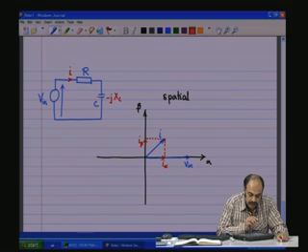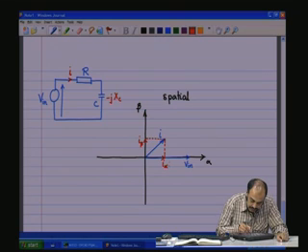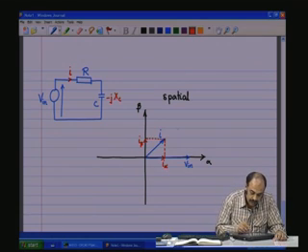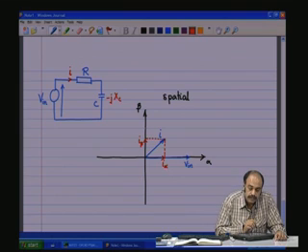So, I alpha into R is the voltage portion which is going to be in phase like that, and I beta is due to the capacitive reactance, and this is the resultant current due to the in phase component and the out of phase component of the current. So, this is how the vector diagram would look for an RC circuit.